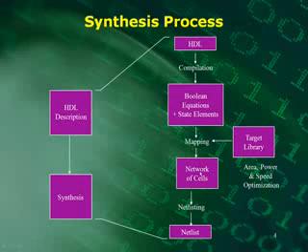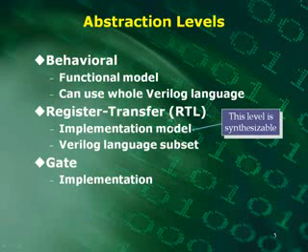It'll run through the mapping, and then that might produce a network of cells, and after that, typically you might make a net list. Finally you get down to this net list that has all of these vendor type library gates in it, and then they're all connected together. So it's just like a sea of gates all tied together. Okay.